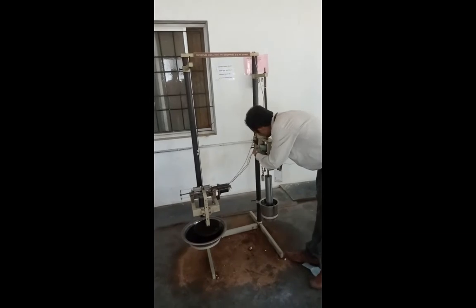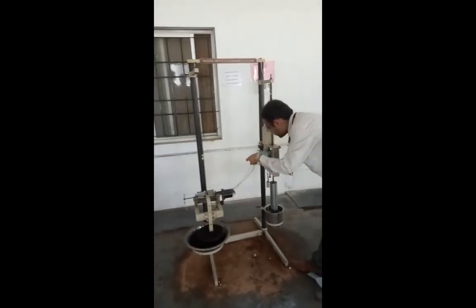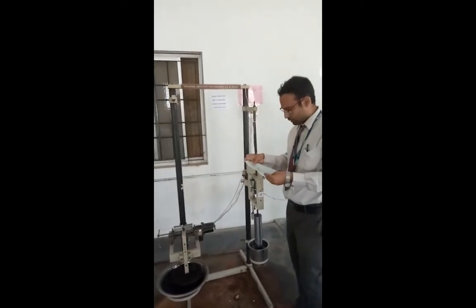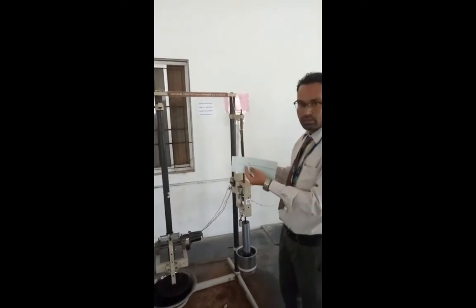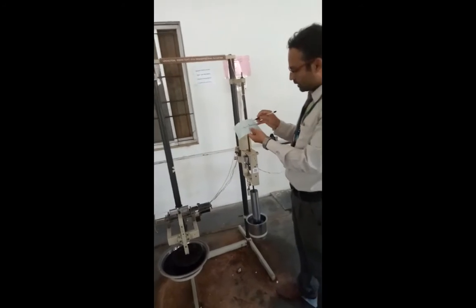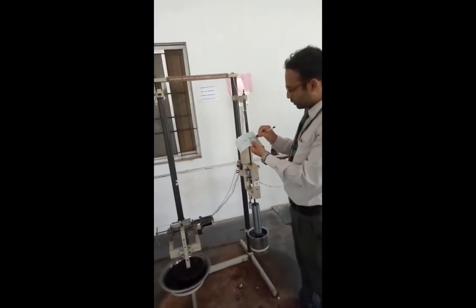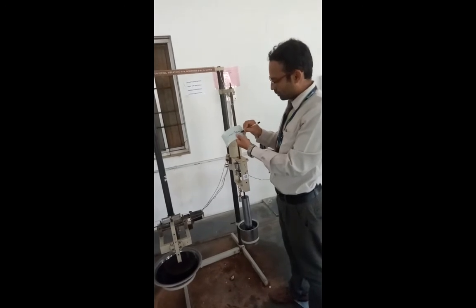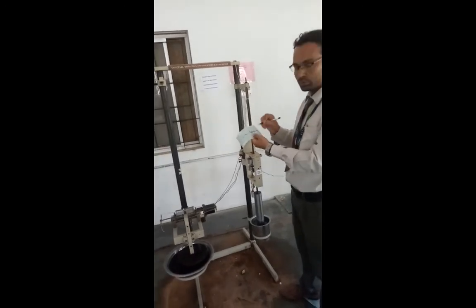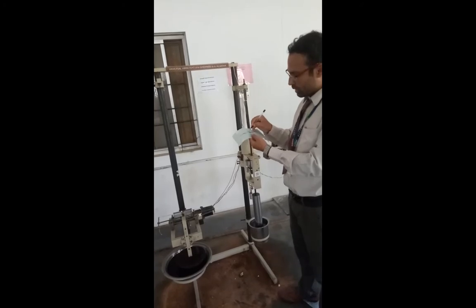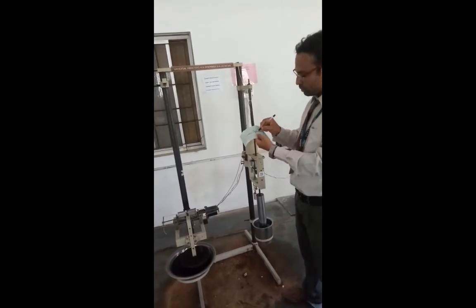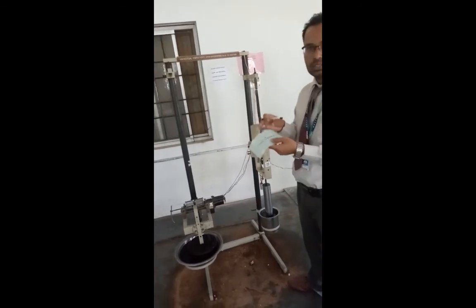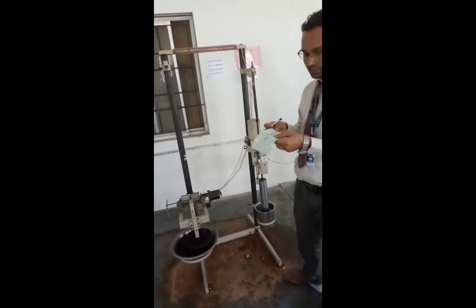After removing this graph, what you get is the longitudinal vibration occurring in this component. Take any one cycle. One cycle is called the time period. From this point to this point, measure with the help of a scale and use it in the calculation. The top side is assumed as x1, the bottom as x2, and one cycle is considered as xt. You use that value to find the time period in the given aim of the experiment.